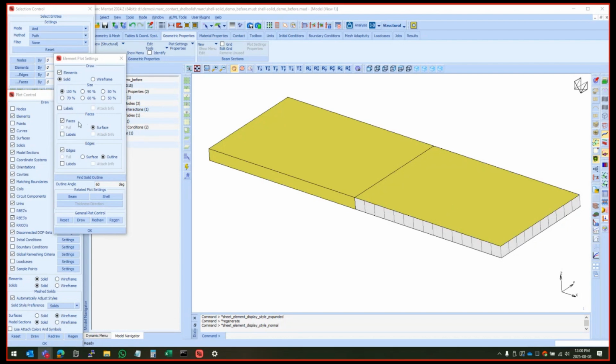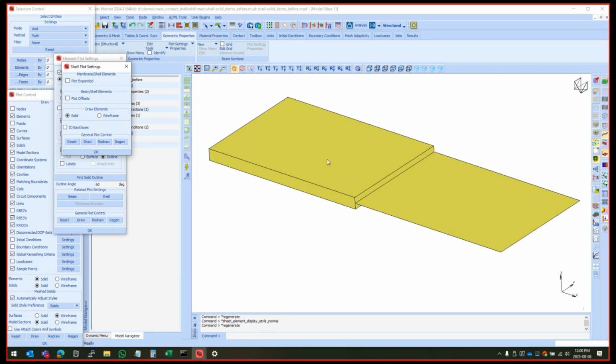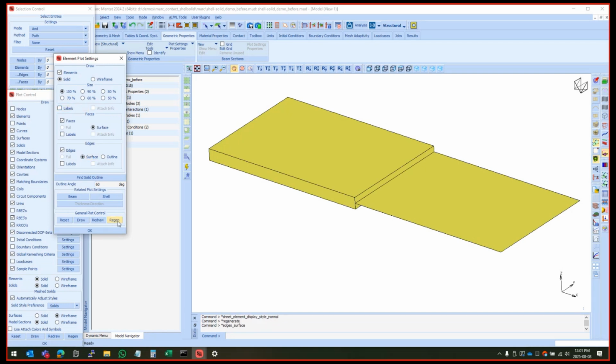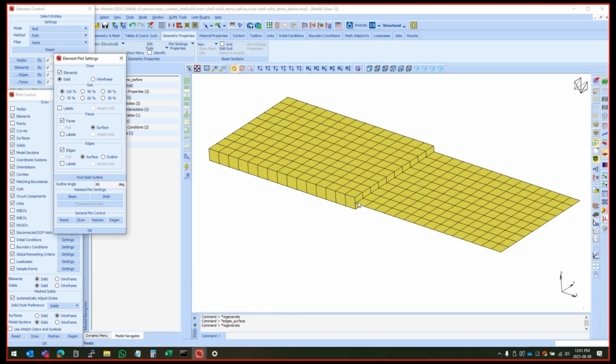Okay, so the idea in this session is to talk about connecting solids and shells together. So that's my shell mesh and my solid mesh. And in this specific example, some of the others, they will not tie up. In this one, they do tie up. So you can see there's one element in that direction for every shell that there is for a solid.